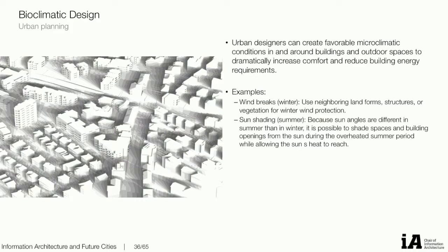Or on the other side, you can use sun shading, so you can make different calculations of what the shading analysis is. Or, for example, in the picture I have here, this is a simulation of a shadow range analysis during a period of time in a particular place. So taking this into consideration, you can make design decisions.